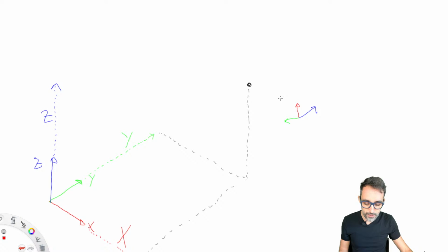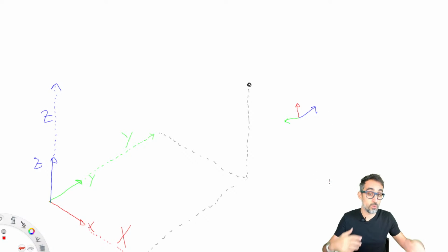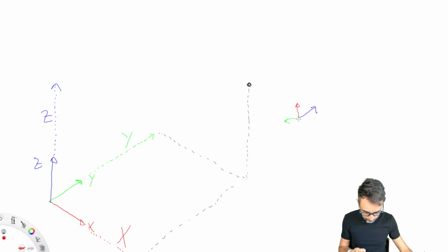So let's imagine we have a coordinate system somewhere in the world, and the way to define it will probably be something like defining where the center, the origin of that local coordinate system is, and which direction the three main axes, x, y, z, for that local coordinate system are. All right? If that's the case, then I may want to find this point, which has global XYZ coordinates, and ask what the actual coordinates of that point are in reference to that local coordinate system.